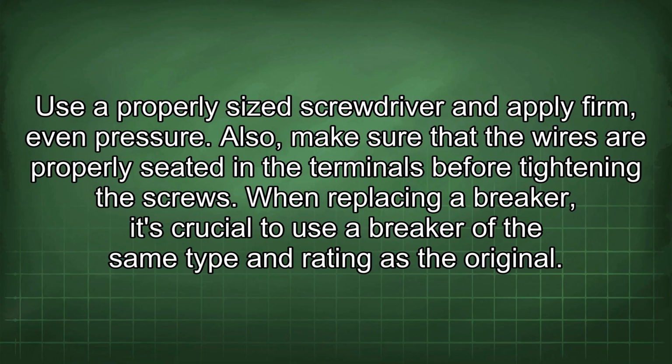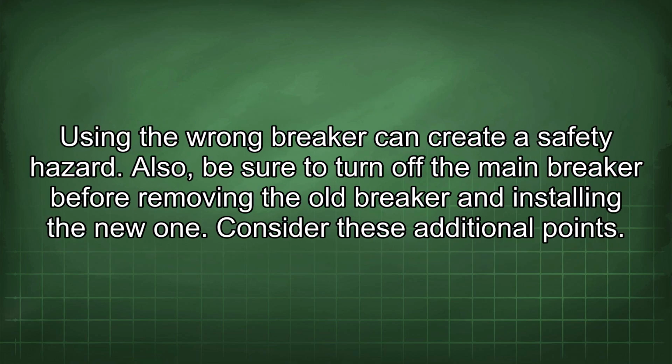When replacing a breaker, it's crucial to use a breaker of the same type and rating as the original. Using the wrong breaker can create a safety hazard. Also, be sure to turn off the main breaker before removing the old breaker and installing the new one.